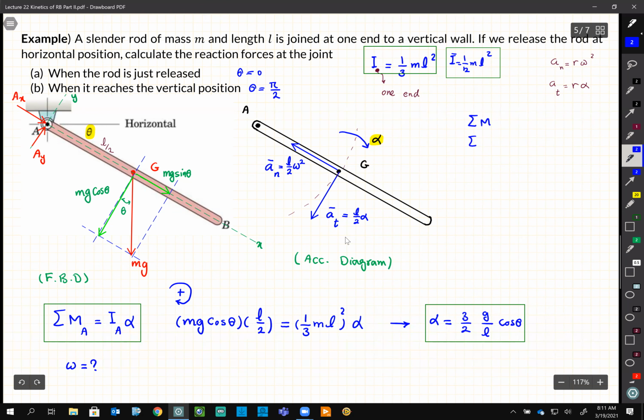And then some of the force equation, m a-bar, and this one I-bar alpha. Or other equation, like here in this scenario, we will use I_A alpha and we write the equation about point A. So if I look at my a-bar, I can notice that I have omega here. So I need to figure out the speed of this link. So I have some formula for omega.